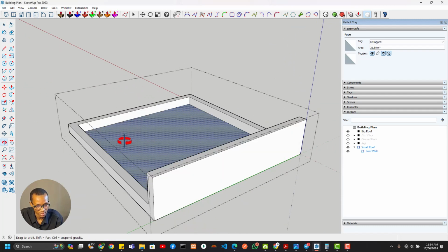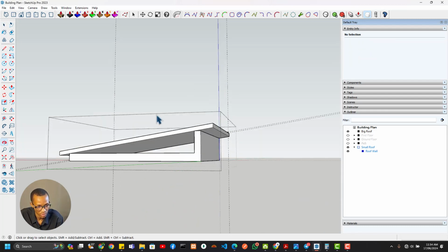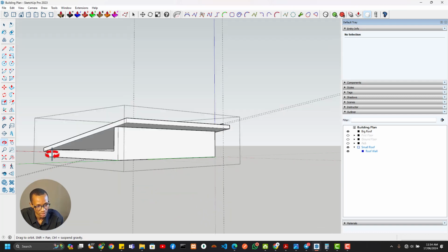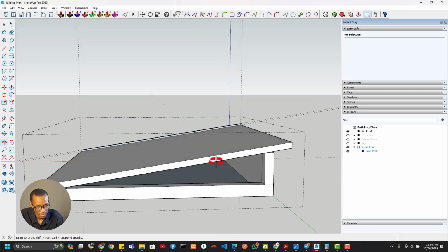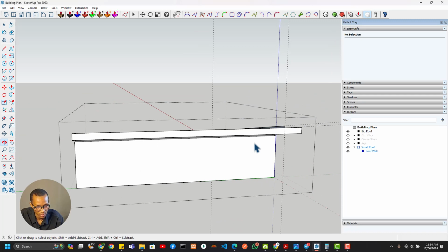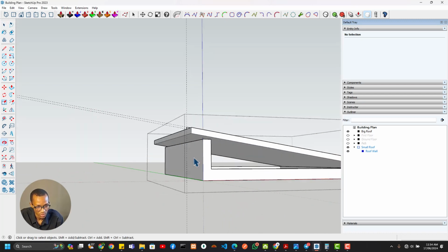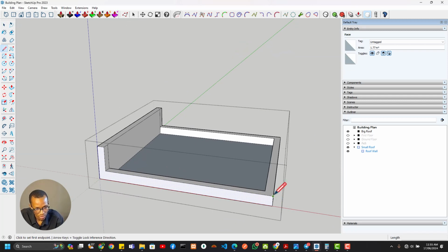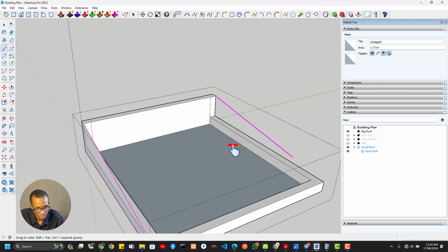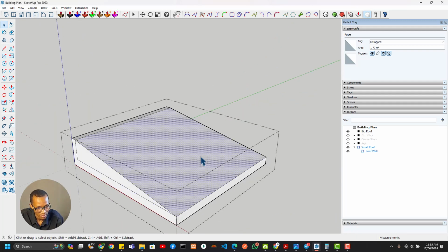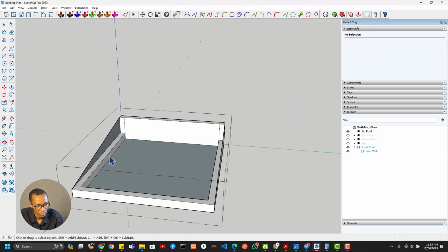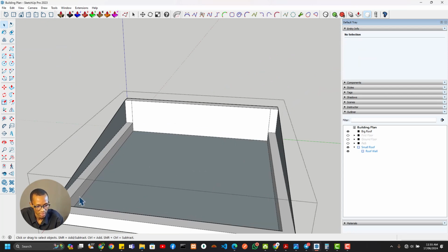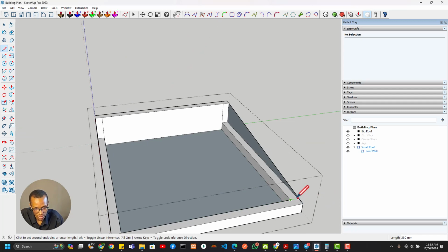The reason I reverse that so it's facing underneath is so that it will serve as the roof, right? So I could leave this hole empty. I could decide to close it, but I'll close it on this side. So I'll come to this wall, and I'm just going to draw a line from this point to this point, and I'll do the same from this point to this point. I don't necessarily need to do any detail in there. You could decide to do all those things if you want to, but it's not necessary.